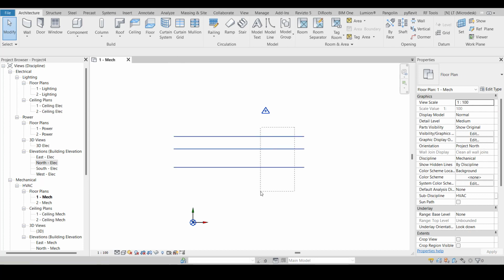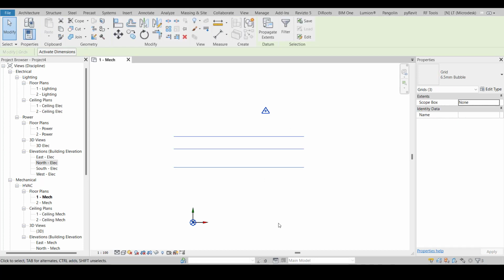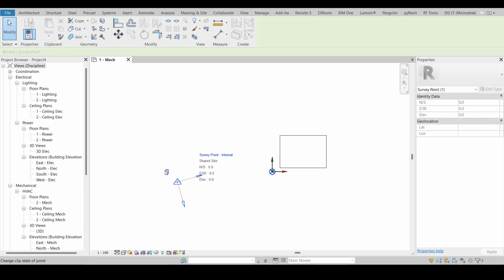So first task is, if you have the checklist, first thing you will see is whether your coordinates are correctly set up or not. If you're an architect, you have to do it manually, the way we have learned in the last session. Now in the second scenario, if you already have a file with correct Revit coordinates, then you can do two things. Either you can acquire the coordinates or you can publish the coordinates.